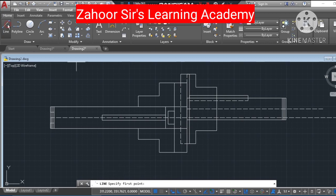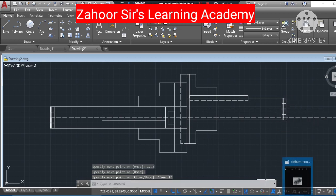So I'll go to the line command, taking it down 12.5, then pressing enter and dropping it there, escape, and then again the line command, 12.5, then enter and dropping it there. Okay, this is how we have done it.